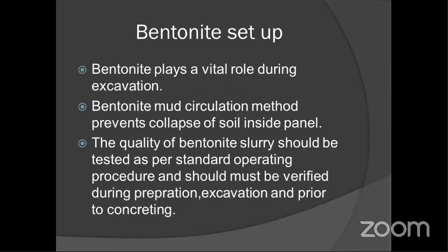See, bentonite setup. As I've seen, the bentonite is going to prevent the collapse of the trench. So it plays a very big role in our construction of the D wall. The D wall works with a bentonite mud circulation.